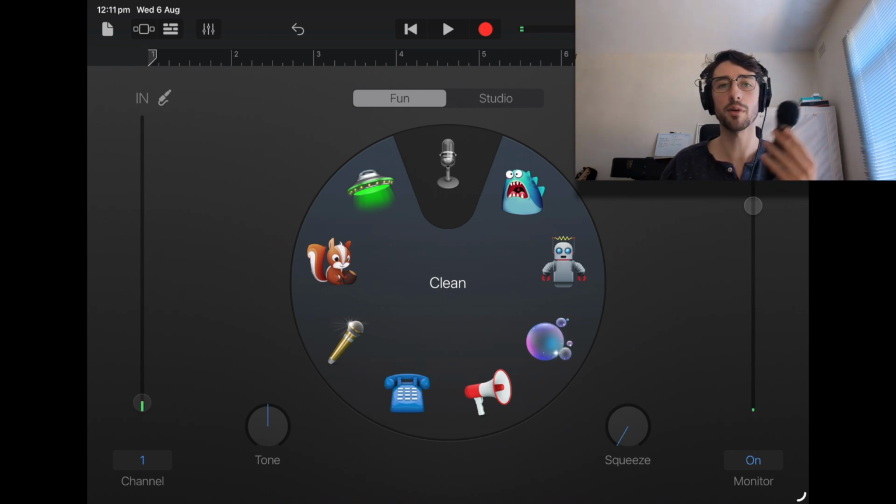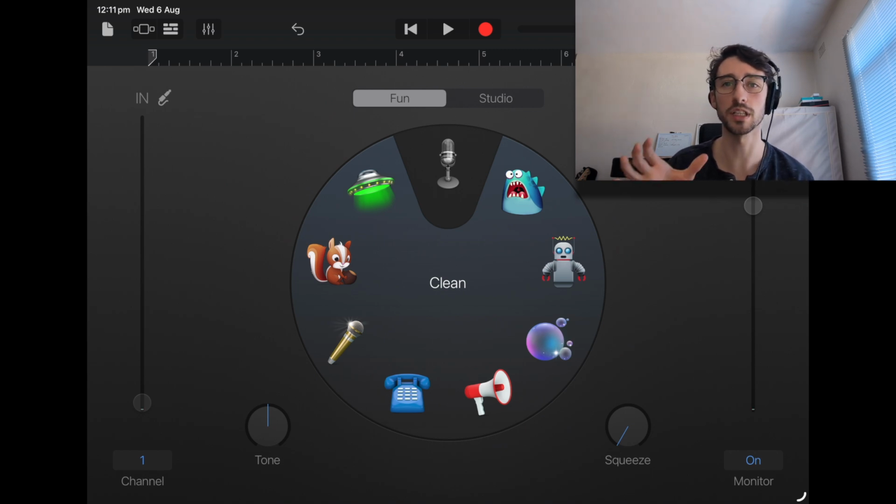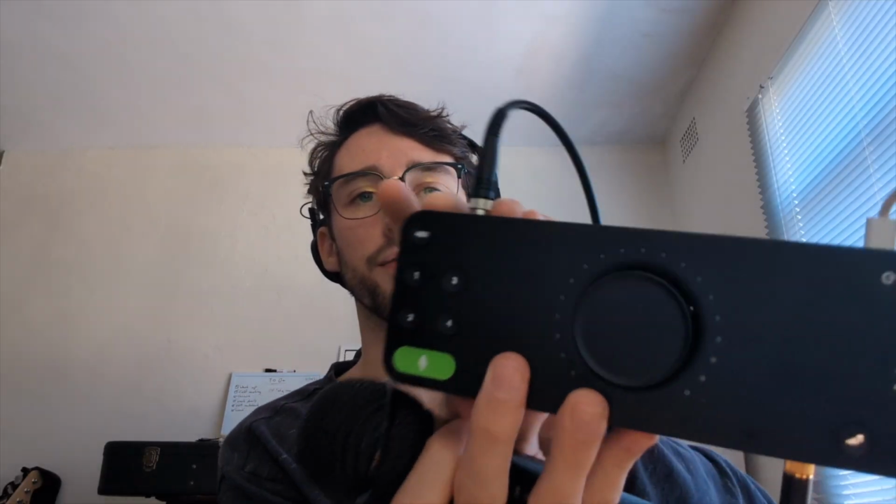This is a dynamic microphone, which is one of the more common styles of microphone you're likely to encounter. Essentially, this means it won't need any extra power, known as phantom power, to run. If, however, your microphone is a condenser style of microphone, or you're just not sure and the output level seems too low regardless of how much extra gain you apply, you may need to activate phantom power on your interface. This is often represented by a 48 volt symbol, which I have here. Fortunately, this microphone does not need that power.